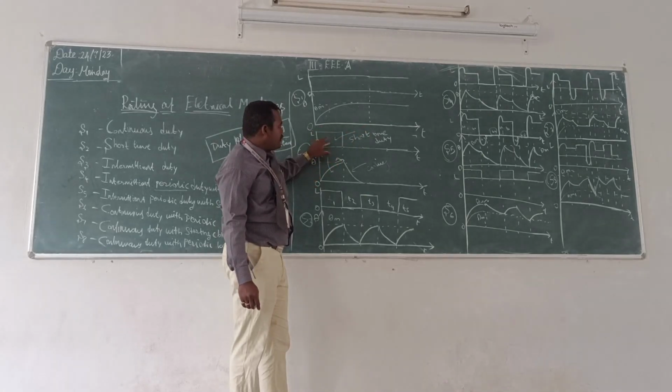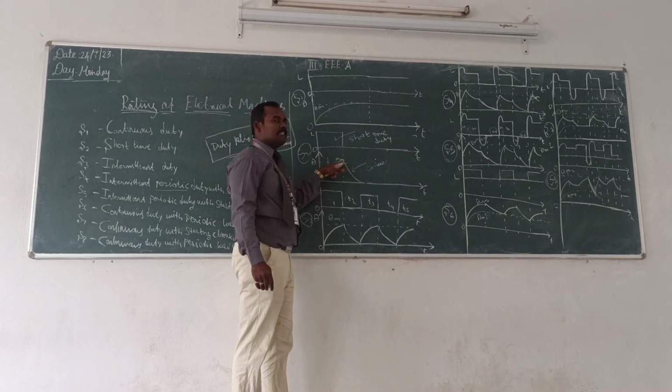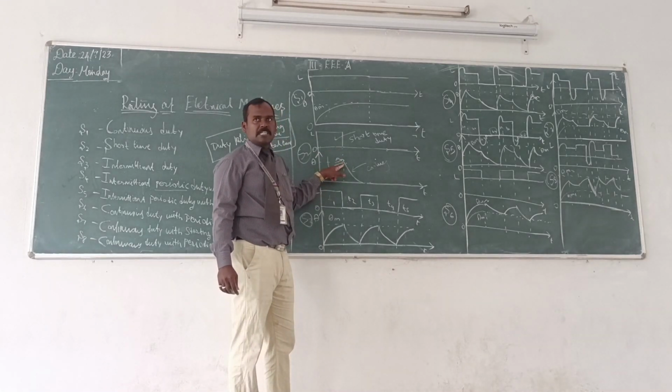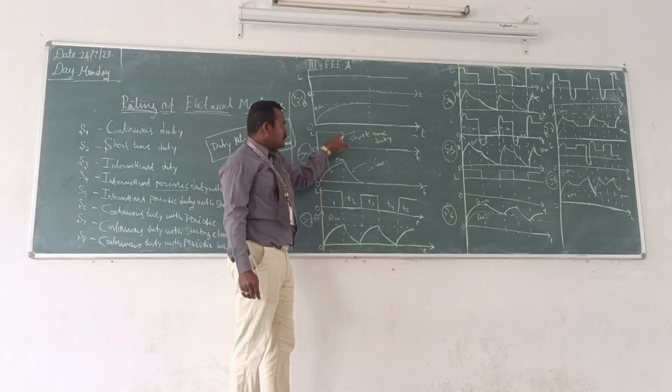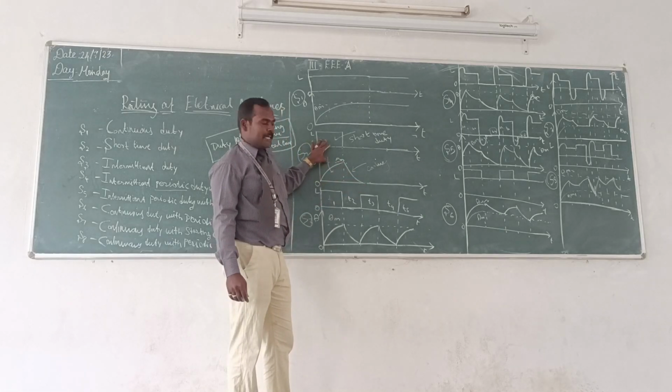In this case, while you are applying the load, the temperature rises and reaches the maximum steady state temperature theta m. After that, the machine goes to rest, so the temperature falls from theta m to 0. That is the short time duty, right?